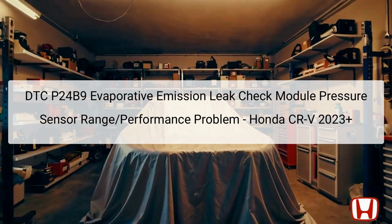The DTC P24B9 indicates a problem with the Evaporative Emission EVAP leak check module pressure sensor's range or performance. This specific diagnostic trouble code is triggered when the Engine Control Module, PCM, detects a significant discrepancy between the measured pressure sensor value of the Evaporative Leak Check Module, ELCM, and the barometric barosensor value.